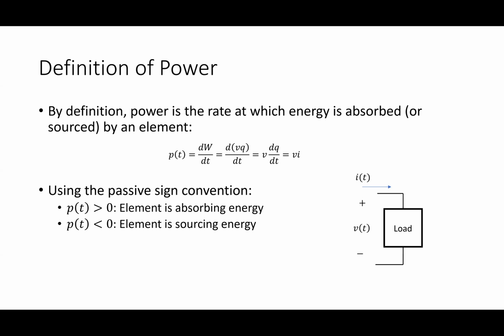Can a load ever source energy? It can, if it's got energy storage. If I have a load, what does it have to be to always absorb energy? A resistor. If I have some inductance or capacitance, it's also going to be sourcing some energy from time to time. That's what Q represents. You guys remember P and Q? Q represents the fact that this load has energy storage inside of it.